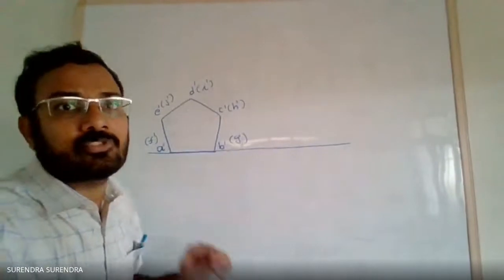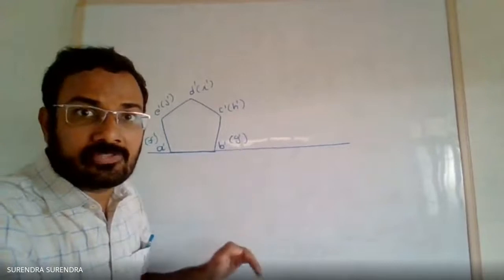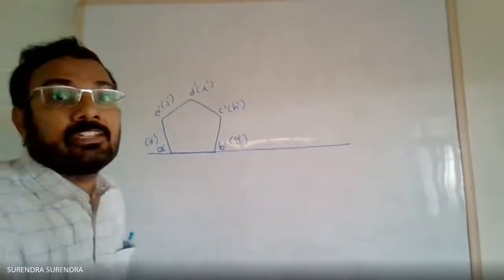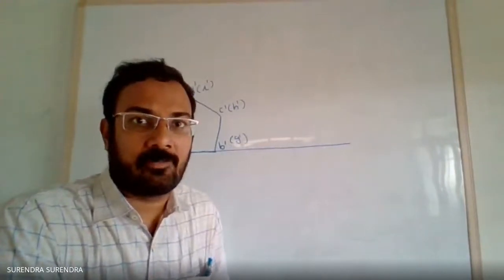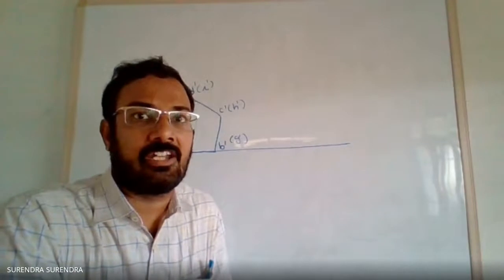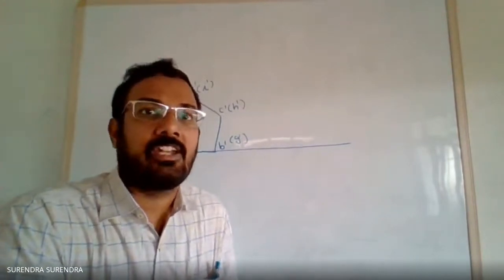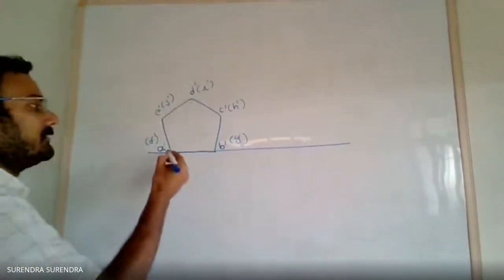Draw its respective top view. For drawing the respective top view, draw the projections from each and every point. The distance from the vertical plane is not given, so you can maintain any random distance. Better to maintain a standard value, what we are following, that is 20 mm.